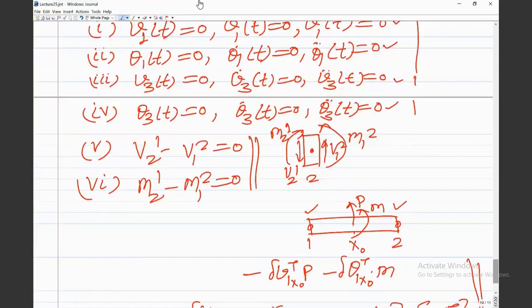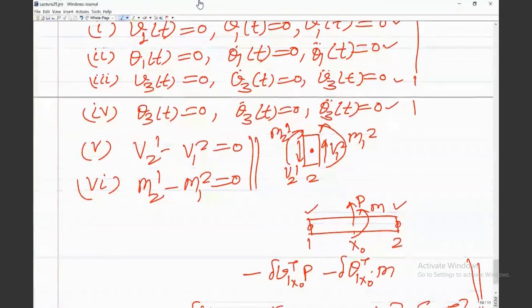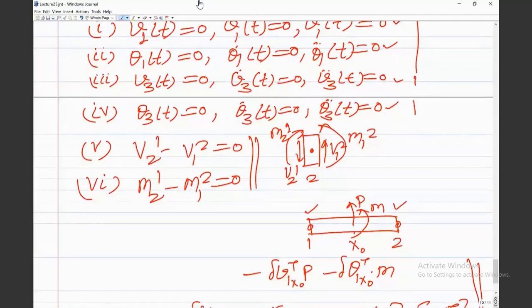Okay. So any other question? Sir, I have one doubt regarding the homework you had given in the previous class. Since it was a one-dimensional problem, we do not need to consider the body force term in the elemental level equation. You will have force per unit length along the x direction, so that you have to consider. Okay, so as a traction, we will have to consider that term. Yeah, in place of traction, you will have forces at the two end nodes, and in place of body force, you will have force per unit length along the x direction. Okay. Thank you.